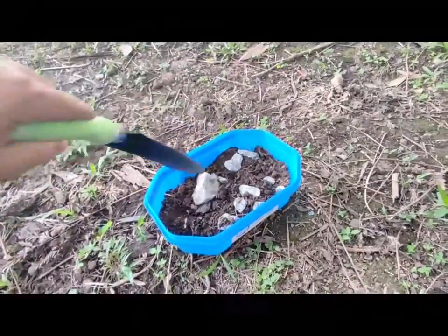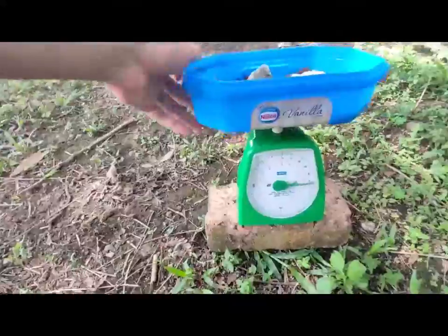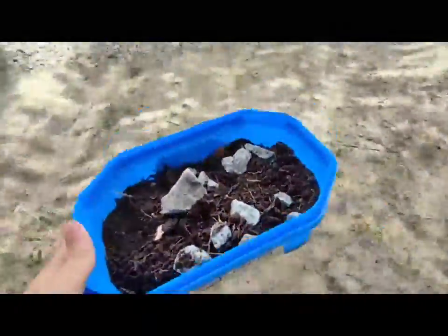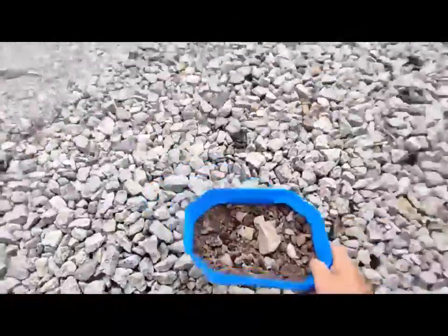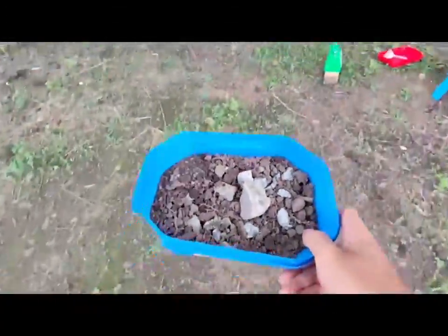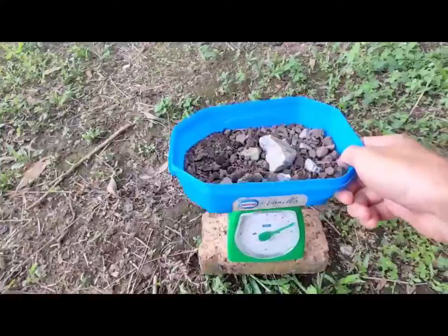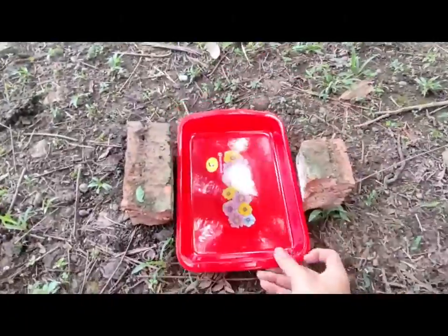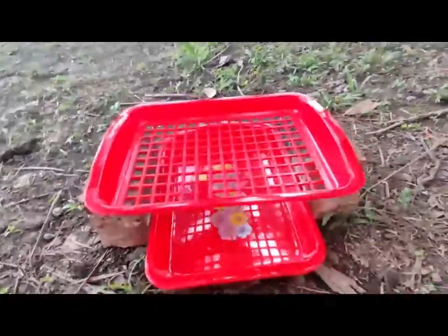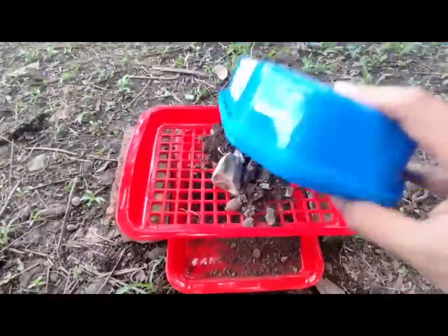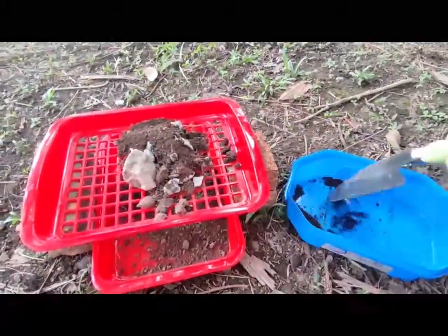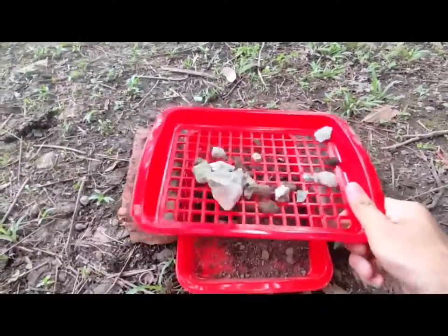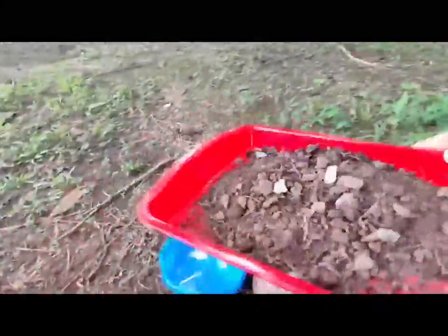For the procedure of particle size grading and texture, firstly, I chose the dry sieving method for my test. Then I take a soil sample and dry it under the sun for 4 hours. After that, I run the soil through different sizes of sieve, and then I record every sieve with the retained soil and tabulate the data.